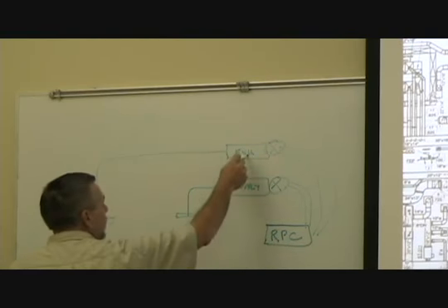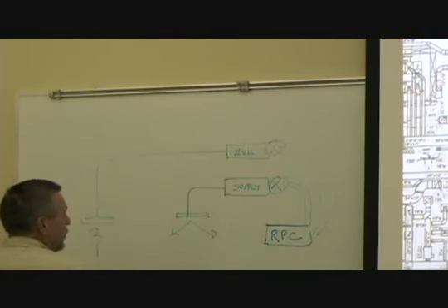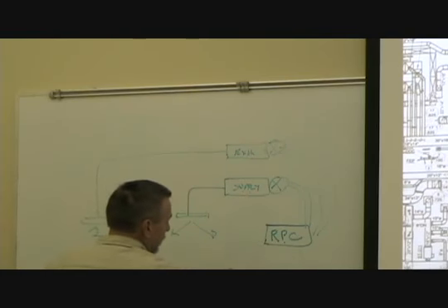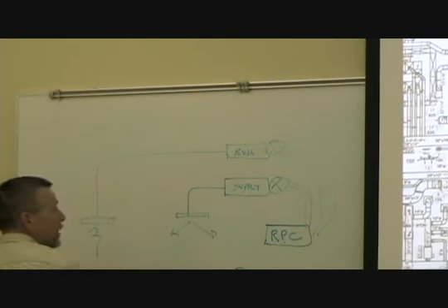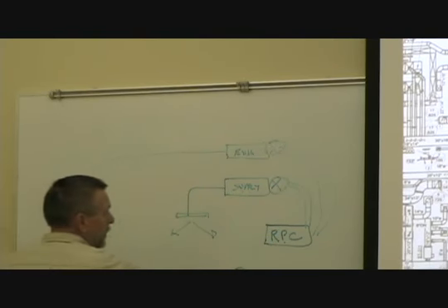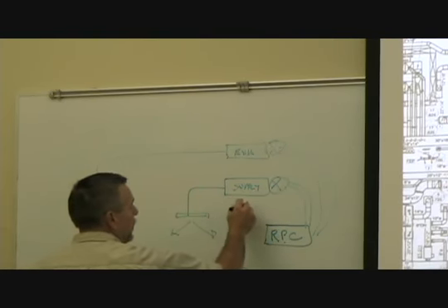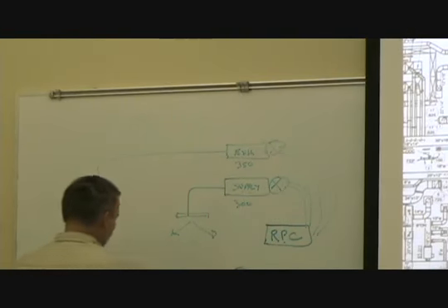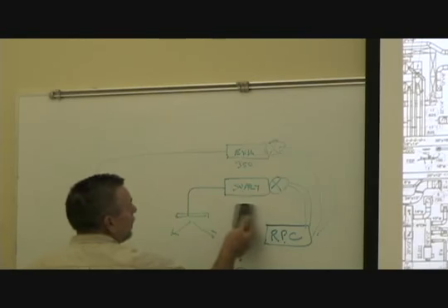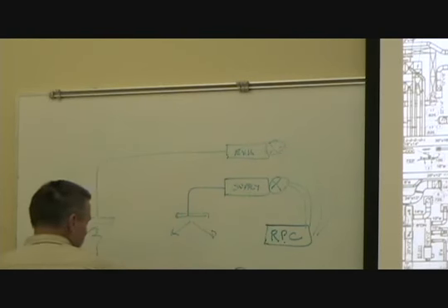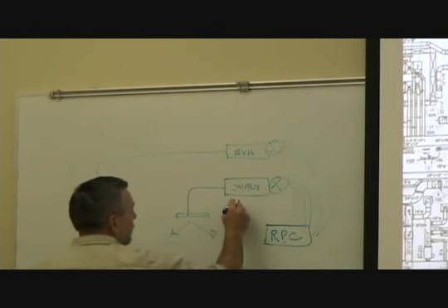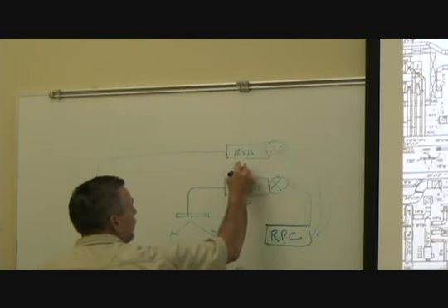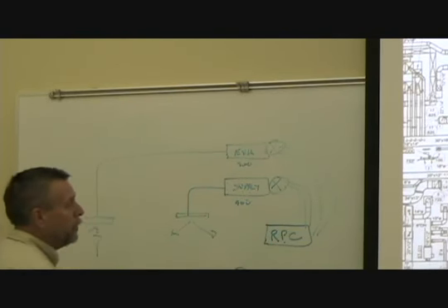So what it does, it measures the supply and exhaust airflow, and through the programming, I either want a positive or negative pressure relationship. If it's an isolation room in a hospital, I would want a negative pressure relationship, and I would program that to be 300, maybe that to be 350 or 400 CFM. In an OR, or a positive protective environment room, might be just the opposite. This is 400, this is 300. And the balance goes out the door or through another exhaust grill, or generally out the door.